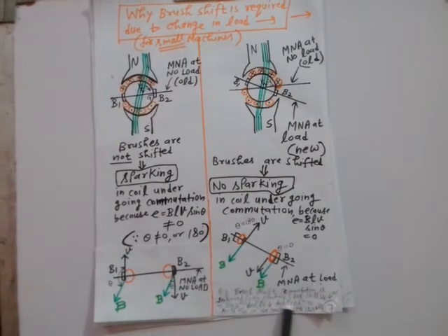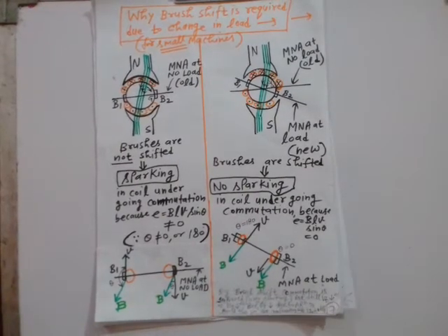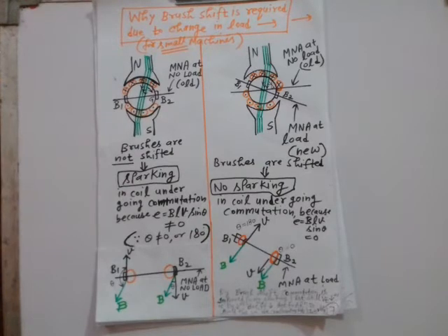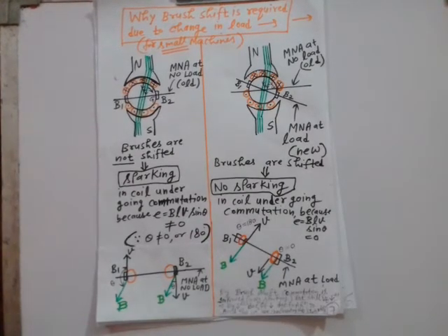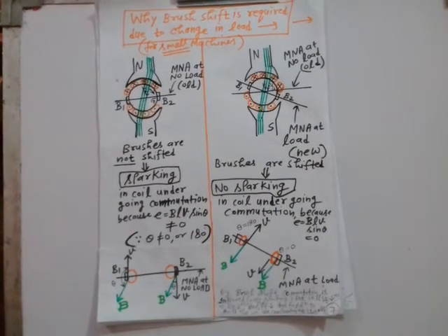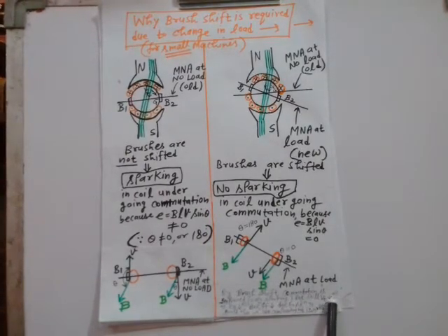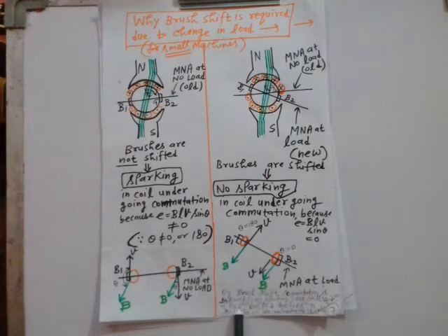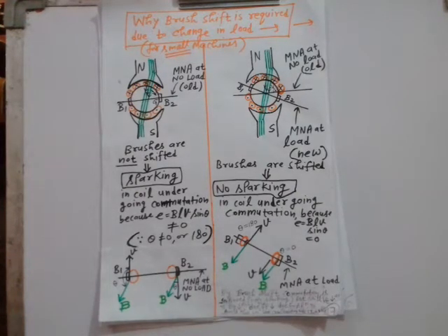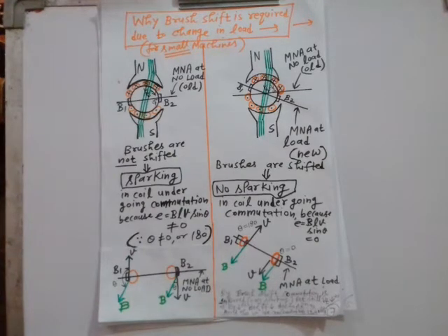But still the terminal voltage is decreasing, right? The terminal voltage is reducing because the generated EMF is reducing, because the field flux is reducing due to armature reaction. I have already explained this. So to avoid all the practical limitations, the brush shift method is not utilized for large machines, for sure, right?